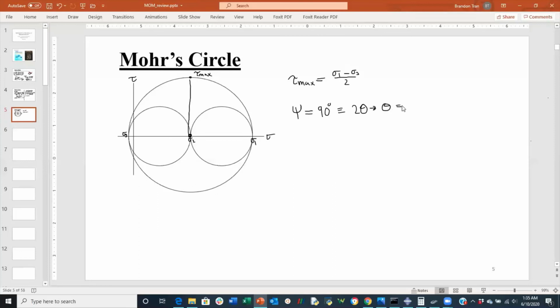in a physical system. And we'll go over this when we go over failures, but typically this has some significance because if you see how a material typically, let's say an isotropic metal, for example, fails when you put it in a uniaxial tensile test, you typically see a fracture that's almost 45 degrees to the face that you're applying normal stress in. So that's obviously an important state to understand.